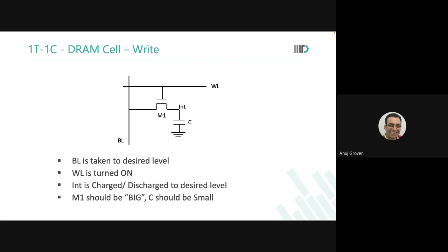But the new emerging technologies that we are talking about, for example, RRAMs or MRAMs or PCM, are all resistance-based methodologies. They toggle the resistance of the memory cell, so the current changes, and you measure the change in current. That is why there is a huge effort to move to resistance-based memories. They appear to be offering more scalability prospects.